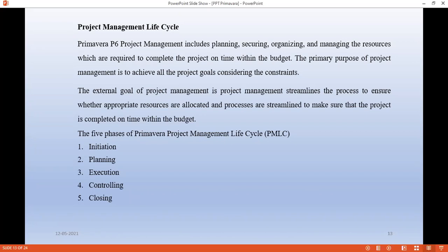When you complete the planning, you are going to get the start and finish of each and every activity, when it is going to start and when it is going to complete. So in planning, you will get the total duration of the project. Along with that, we can get the time duration required for the entire project, and you can decide whether the activity is critical or non-critical. That will be seen in the planning itself, because after making a complete plan of the project, you have to submit a copy of the planning you have done to the client. The client will check it out.